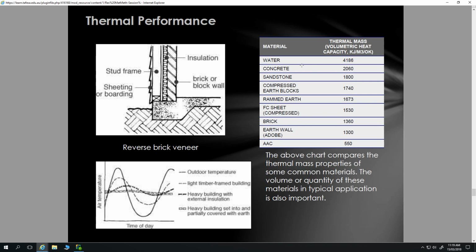That scenario gathers a material which is on our table the highest possible storage, or has the highest thermal mass, and puts that right in the centre of the building. So it produces that thermal flywheel to the building, and also provides water storage.